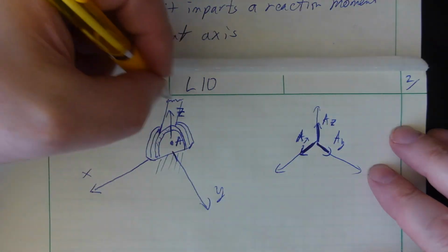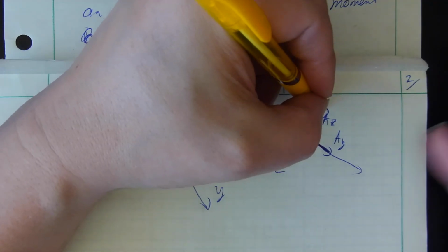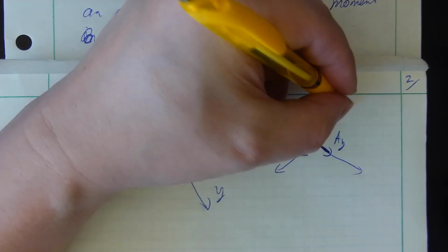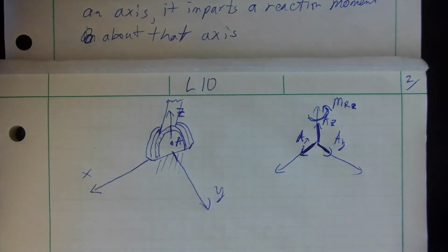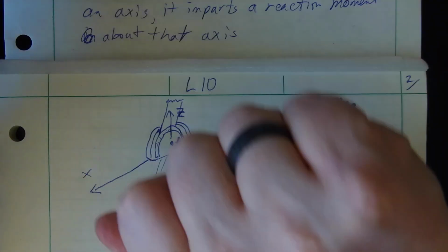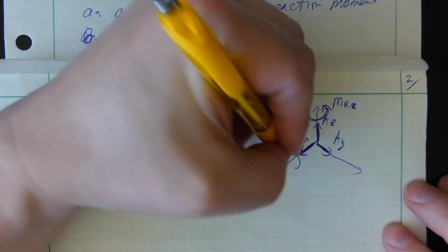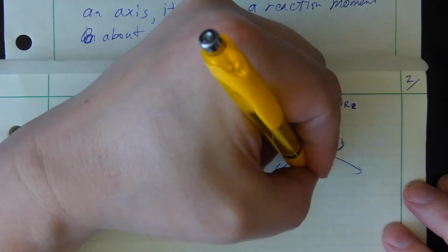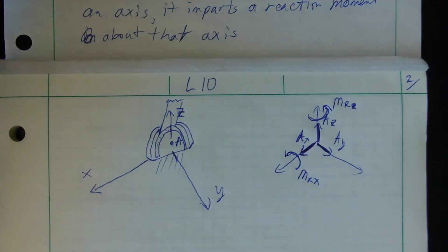I can't spin this thing vertically, so there's a reaction moment in the z. And if I try to rotate it about that x-axis, it won't rotate about the x-axis. I've got a 3D printed hinge here. I'll show you, maybe that helps. I also have a reaction moment in the x-axis because I can't rotate this thing about the x-axis as it's sitting right now.